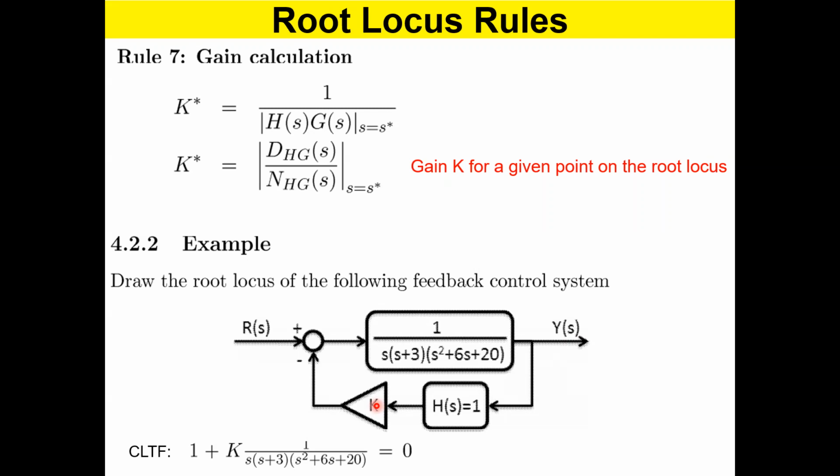Whether it is fastest time, smooth profile from present to the desired value. So whatever it is, you achieve it for a certain value of K. So to find what the value for K is basically the design criteria. So one of the design criteria, a very classical criterion, is root locus design. Okay, so this is how things are connected to each other.